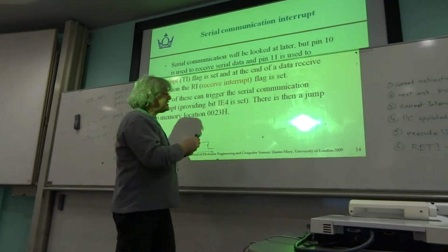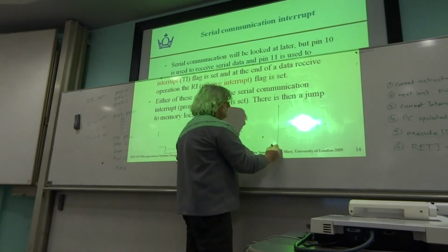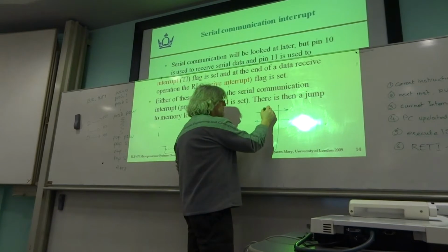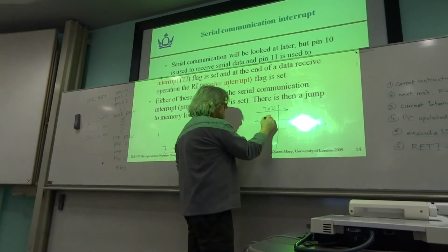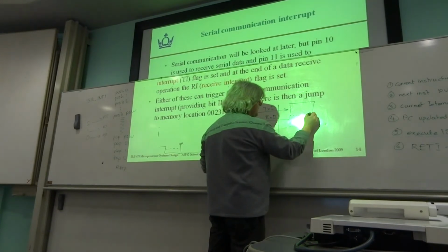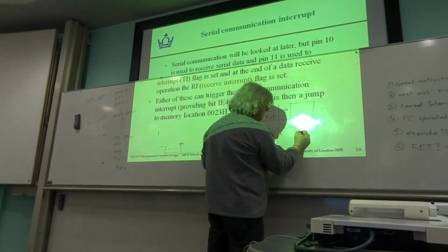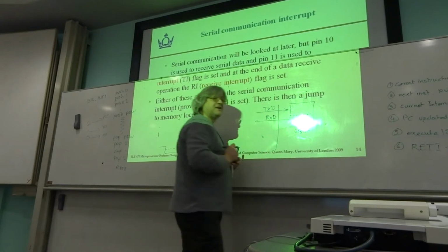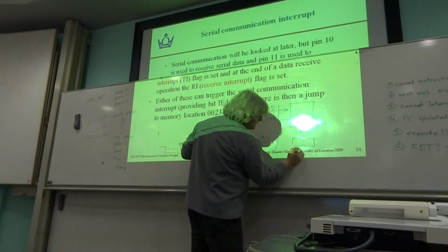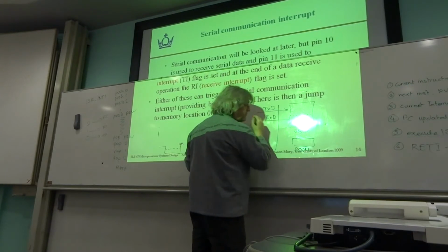And as I said yesterday, with the serial interface, there are 2 pins that belong to port 3, which are used for it, TXD and RXD. And they're both connected to a special buffer called SBUF, where S stands for serial buffer. There is actually a control register for that called SCON that we will go through in a week or two's time.